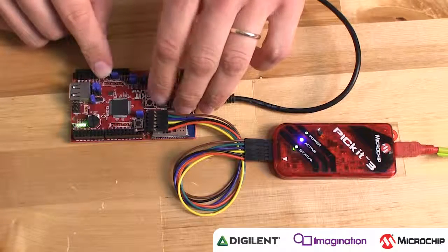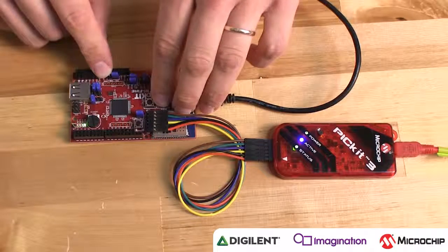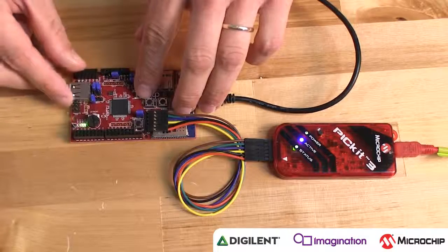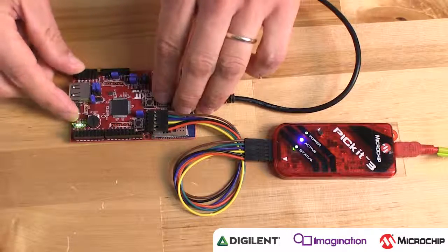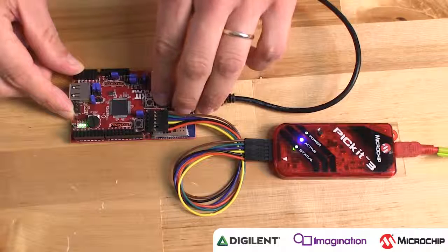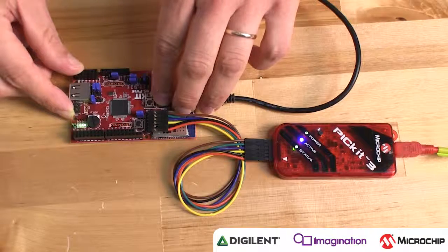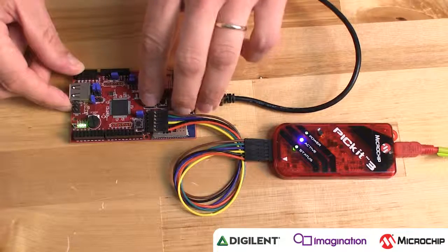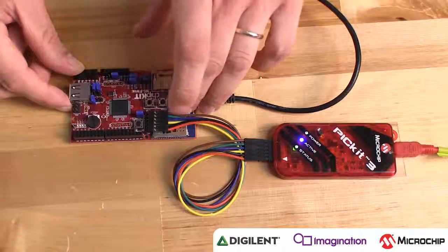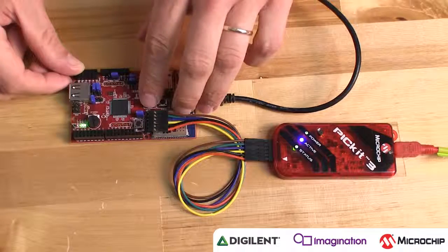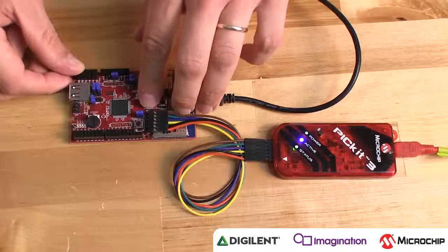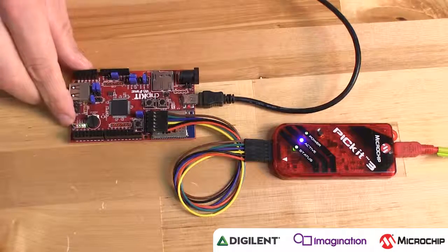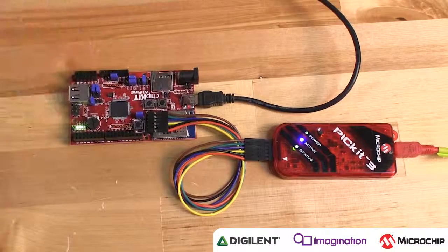So with this code, we have a delay. The switches are only read after the last LED is turned on or off. So if I press the switch here, there's a delay until we get the fast scanning. Similarly, if I press switch 2, there's a delay until they turn off. Press switch 2, then they turn off. We want the switch to turn the LED off immediately, but our scheduling approach doesn't work that way.